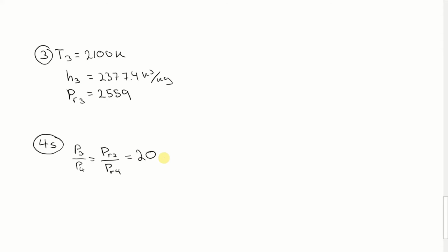And that's actually quite a good assumption, knowing how the real system operates in that schematic shown above, because both the inlet and the exit are taking and venting out to atmosphere. So unless there's something in the question that says you have to assume a pressure drop across the heat exchanger, or it explicitly says that the inlet and exit conditions are different, you can always use the same pressure ratio.